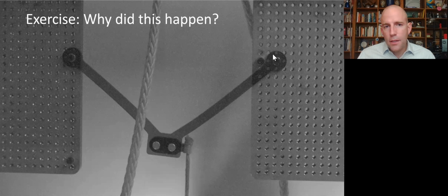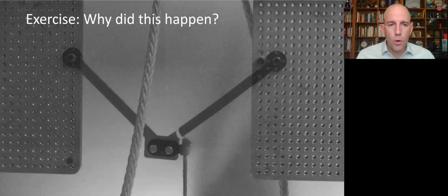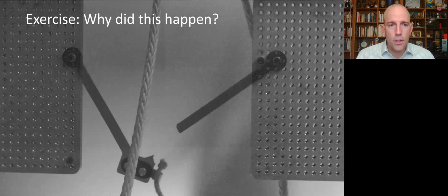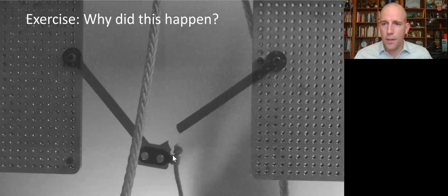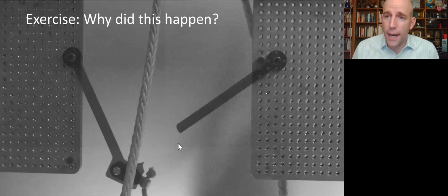And we expect that the moment at these connection points will be small because they're round pegs and round holes. So probably there is a low bending moment here. That means there's probably a high bending moment there. This becomes a sort of cantilever beam scenario. And that is consistent with the way the component breaks eventually. You can see we get fracture where the arm intersects there. That's where the bending moment should be highest.